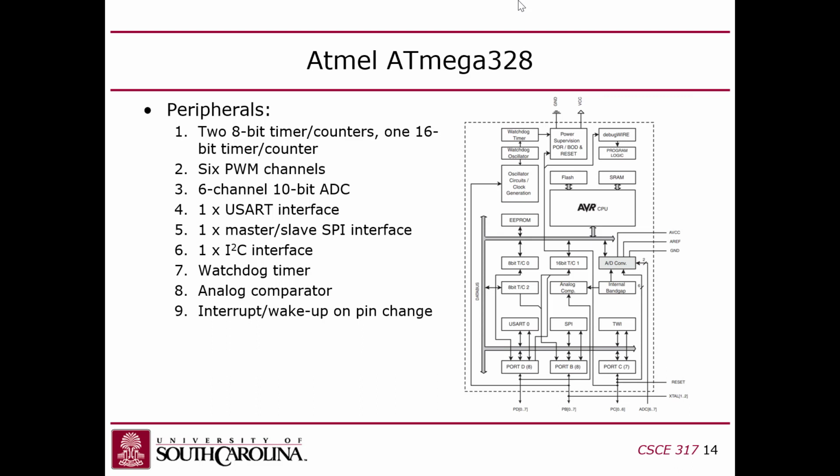There's an SPI interface, which stands for Serial Peripheral Interface, and there's one I2C interface, and I don't even know what I2C stands for. Do you know what that means? It's a standard I/O protocol. I know it's a Philips thing, but I don't know what it means. Actually, Atmel calls this the 2-wire interface, TWI, so you may see it referred to as TWI instead of I2C.